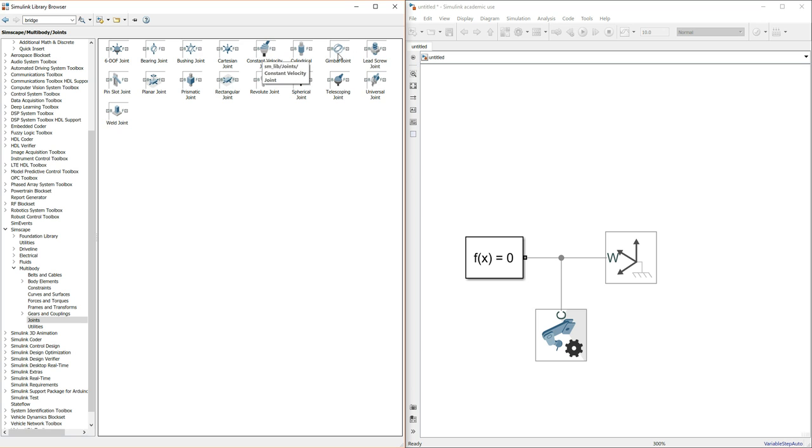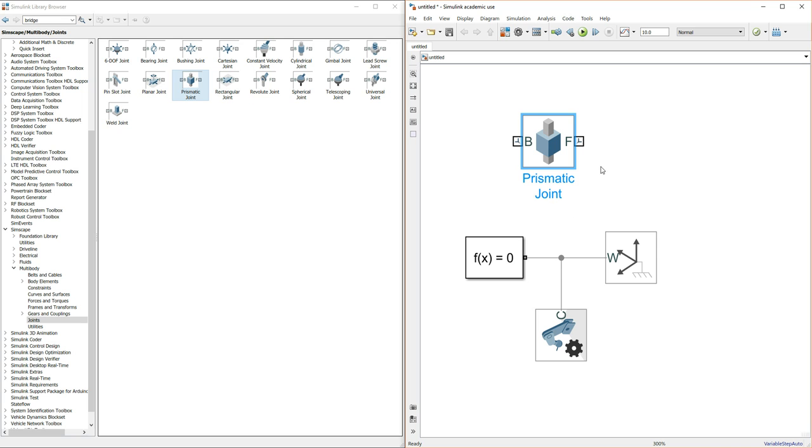So these joints are here to replicate specific behaviors that we're trying to recreate. Now, the nature of the mass spring damper is a linearized format, so it will just bounce backwards and forwards, as we know. So what I'll do is I'm going to drag and drop a prismatic, because when we drop it, it goes straight up, straight down. Hence a prismatic motion. So I'm just going to spin that round. I know some of you were thinking, yeah, but sometimes it's not 100% clear. So I wanted to be 100% before we even moved on.